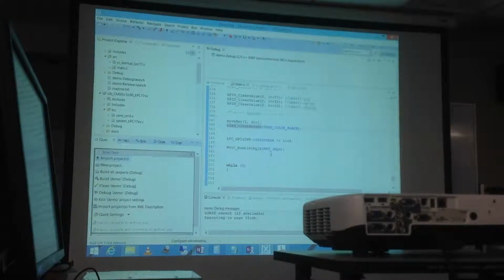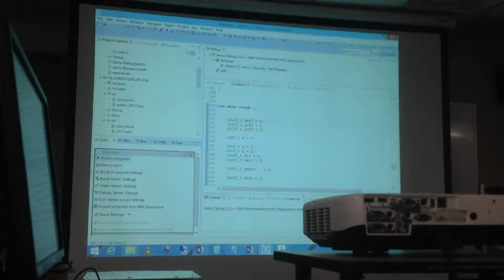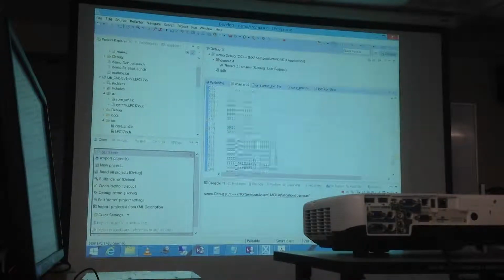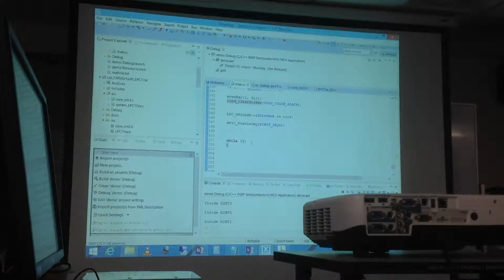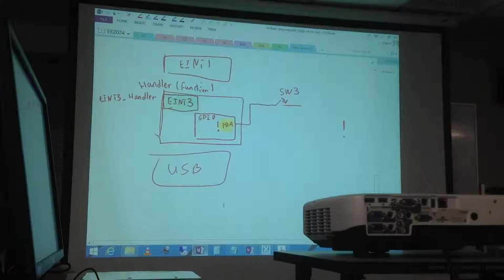So right now, I press play. Let us see. Inside our program, there's nothing. There's nothing being done. Let me try to press SW3 to see if something can be printed. So I will press my SW3, and you have this thing which happens continuously. What is happening here is, when you had pressed SW3, an interrupt signal was set. So here, an interrupt flag was set to 1. Okay?